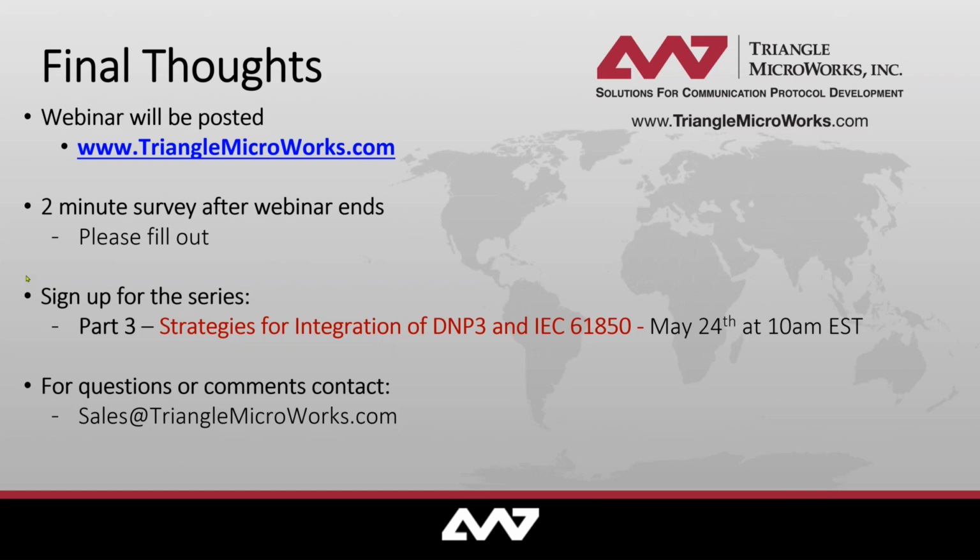Yes. So I think one way to think about it would be an LN is a collection of data attributes, in 61850 terms, variables, points, whatever you want to think of them as, associated with a specific function. So we talked about that breaker failure function earlier. So how a breaker failure function works from manufacturer to manufacturer probably isn't that different, but it could be. But the assumption is that they want to use a similar set of data attributes between them, and they can customize that a little bit in the data template section. There's some required and some not.